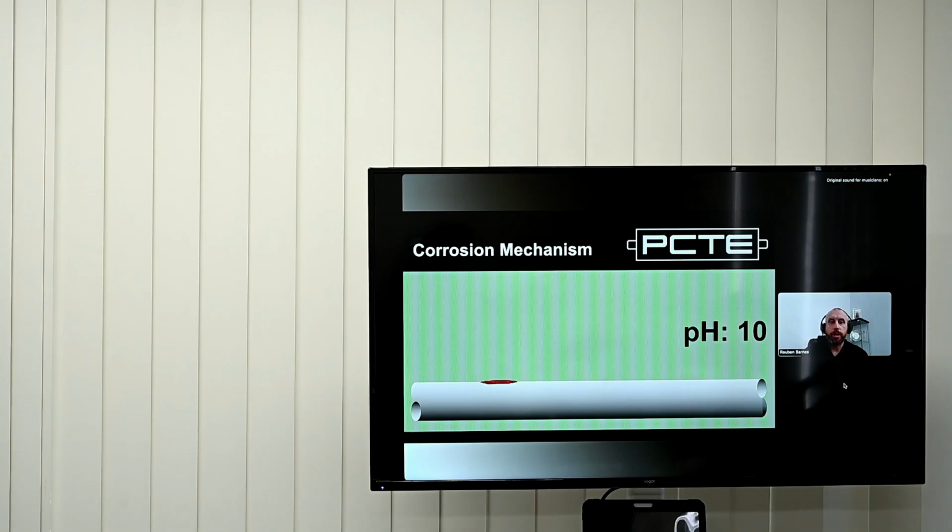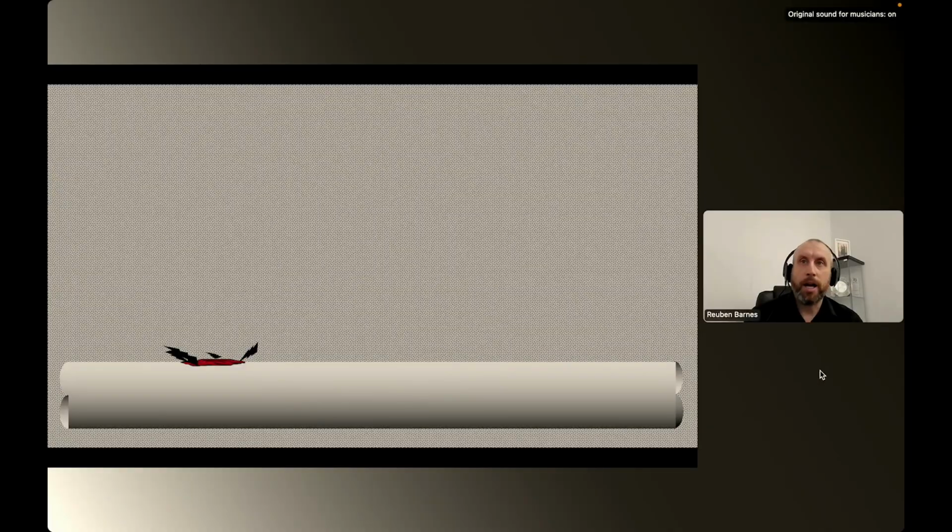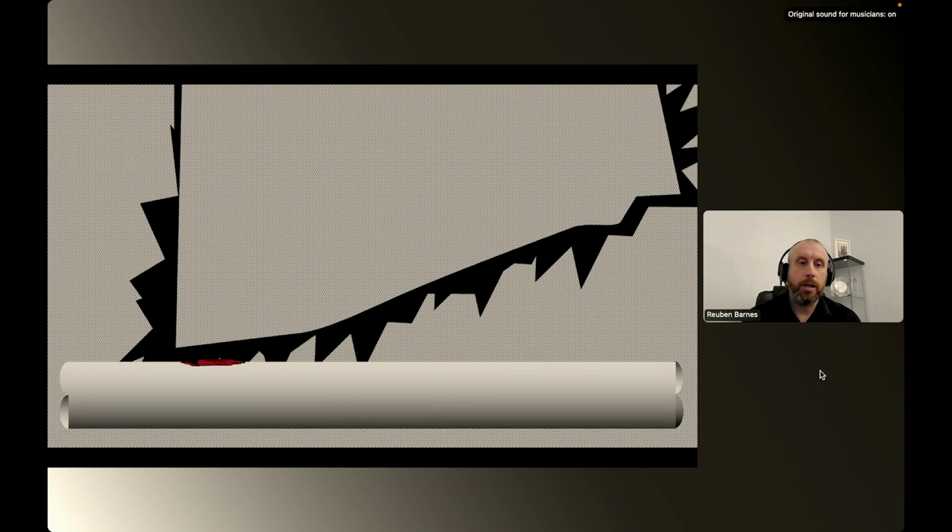Obviously, the detrimental effect of corrosion is that the increased volume is going to create internal stresses inside our concrete. So we tend to find we get expansion, and then we have these stresses and cracking. Once that becomes quite severe, we typically notice either cracking, and once that gets quite bad, we get drummy concrete, and once that gets very bad, we can have spalling.